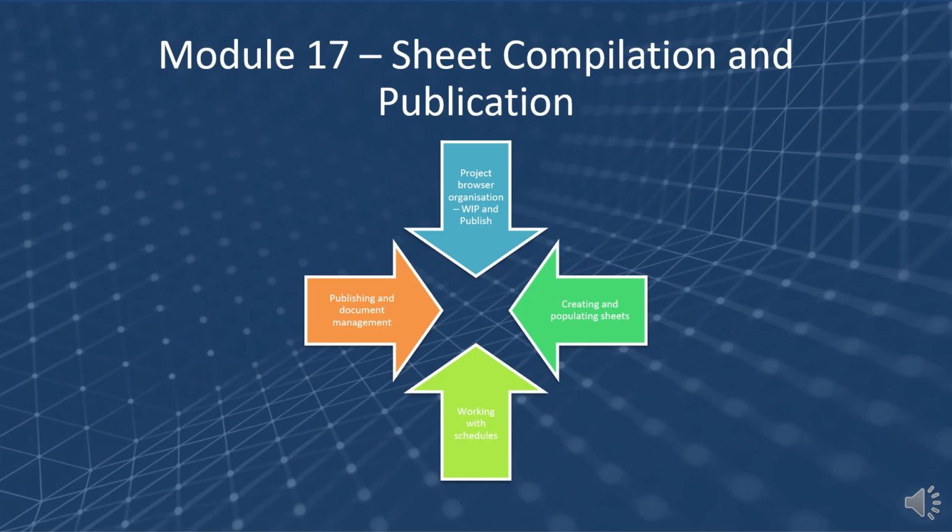Next, we cover creating and populating sheets. You'll learn how to place views, adjust title blocks, and manage sheet parameters to produce clean, consistent documentation. We then explore working with schedules, integrating tabular data into sheets to support coordination, quantity takeoffs, and compliance. Finally, we look at publishing and document management. This includes exporting to PDF, managing revisions, and preparing your model for submission or construction.